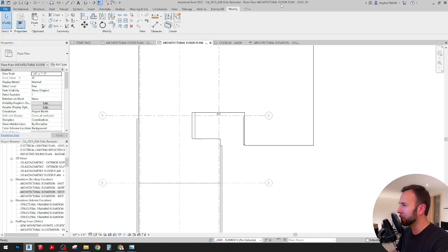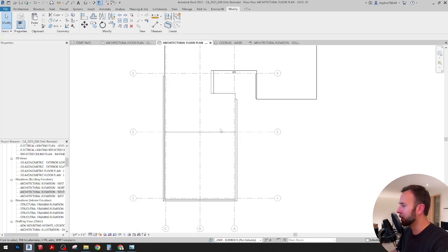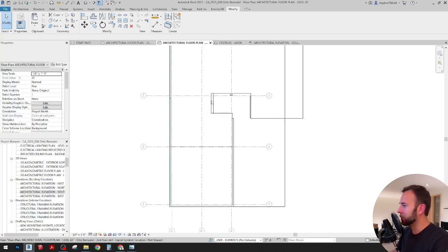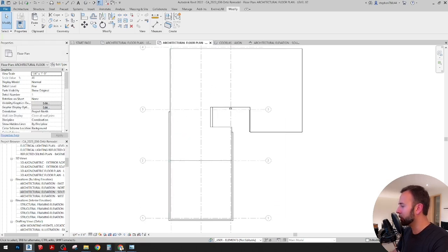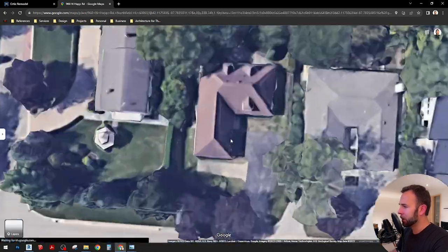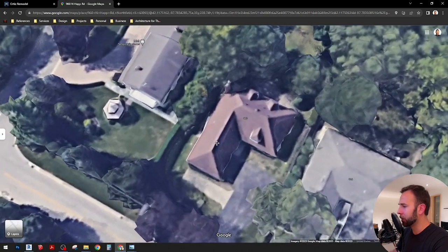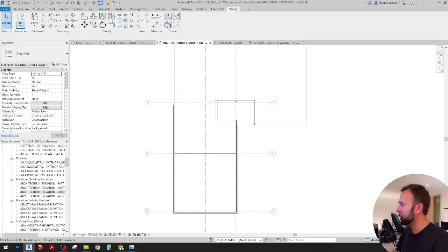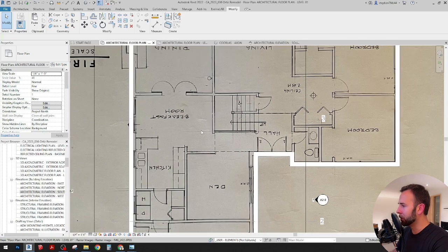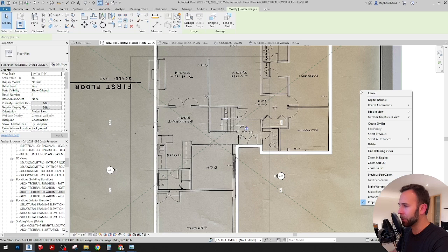We'll go to our level 2 floor plan. We can model in pretty much the whole roof. We just take another look at the shape. I'll see if we can get it in one shot there, not modeling in the dormers right now, but just the primary roof. So it might actually even help to go down below to our first floor plan, because it's got all the perimeter walls. So it was a good thing we modeled the entire perimeter.